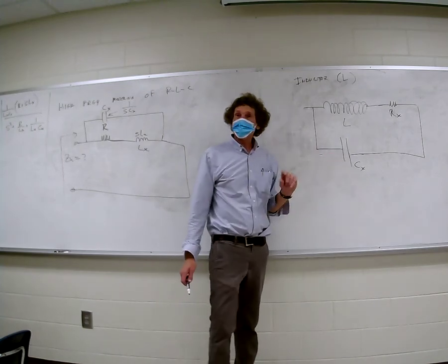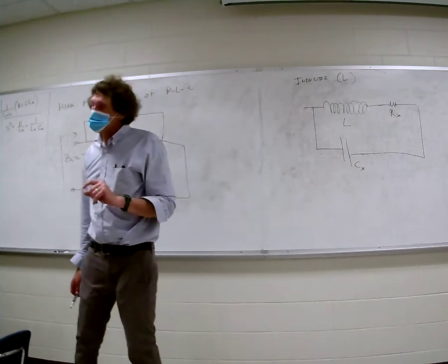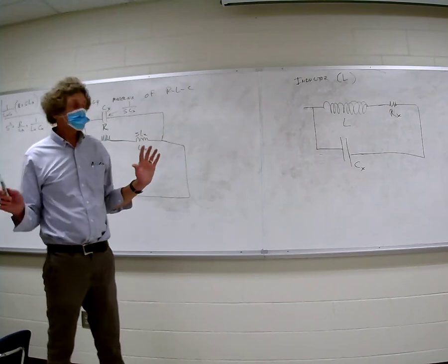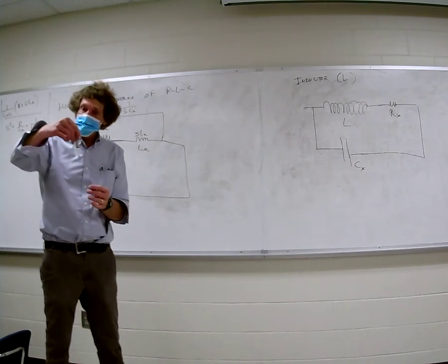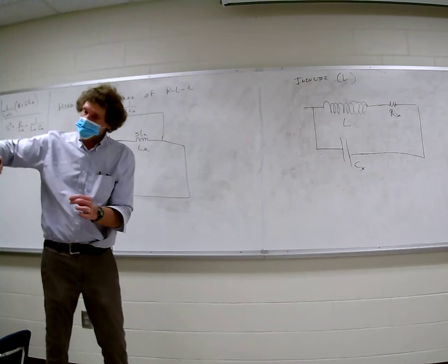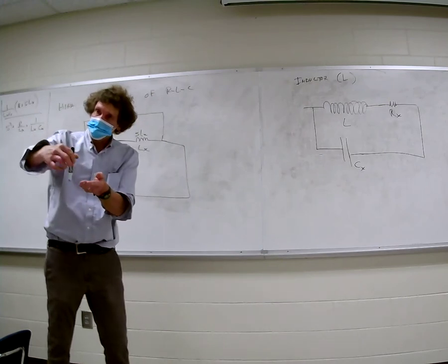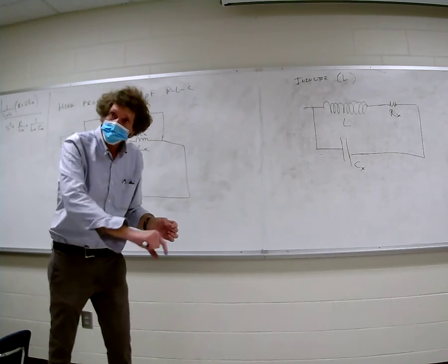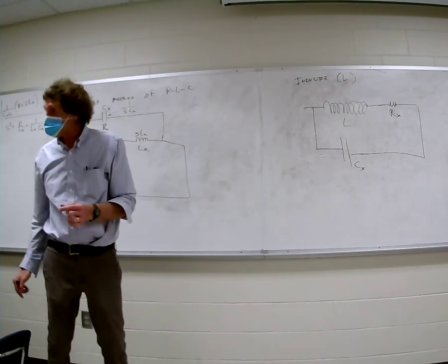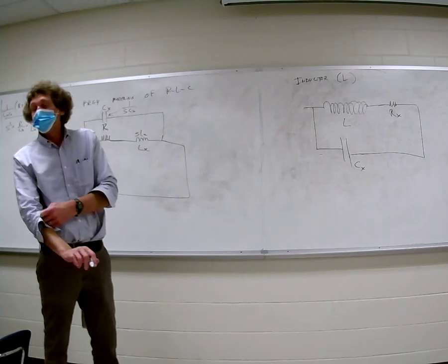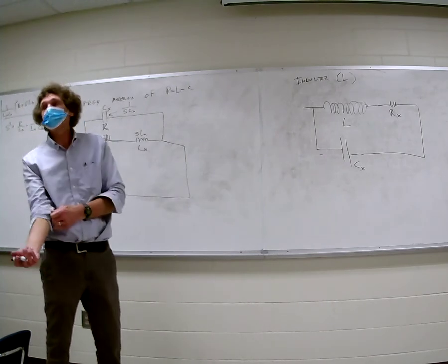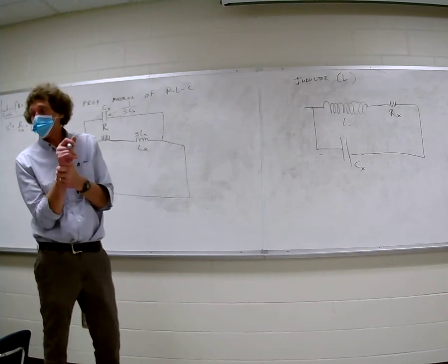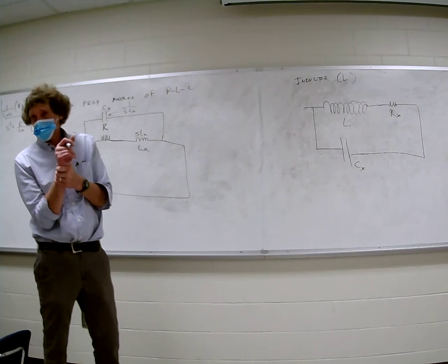The capacitance on the two is usually more, I have to be careful about this on the inductor. The reason is between each winding, every time you get one turn like this, there's shellac or some insulation between, so you get a gap there. That gap has a capacitance that spirals around the entire length of the wire. Without getting into the modeling of that, just remember this: inductors in general have more parasitic capacitance, maybe an order of magnitude more or better than a resistor of the same dimensions.